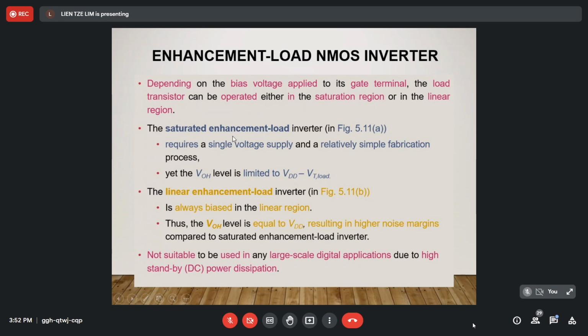The saturated enhancement load inverter in figure 5.11a, the figure that I showed you just now, requires a single voltage supply and a relatively simple fabrication process. Yet the VOH level is limited to VDD minus the threshold voltage.